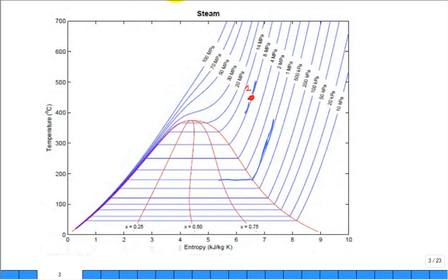As I've sketched it, it looks like if it was isentropic, it would be very high quality steam. True? And so this is what we would call state 2S, and then we would have another state which is our actual enthalpy, our actual state 2. And we've talked a little bit about this because the second law, if you do have some irreversibilities, then what is the exit entropy? It's higher, isn't it? It can't be lower.